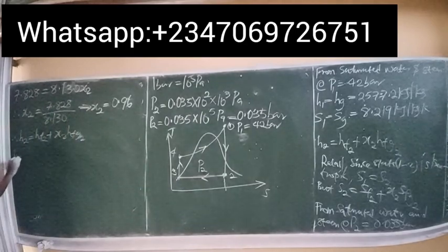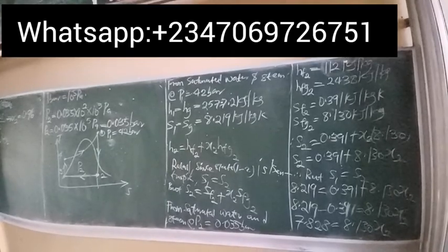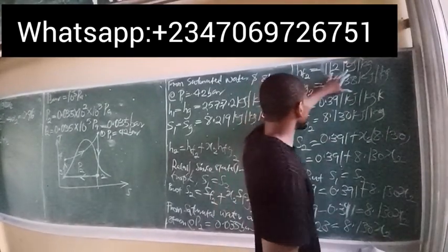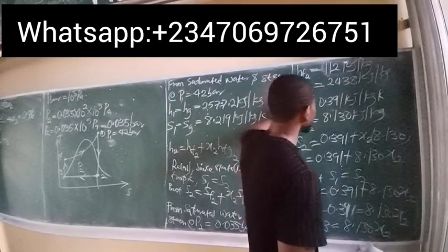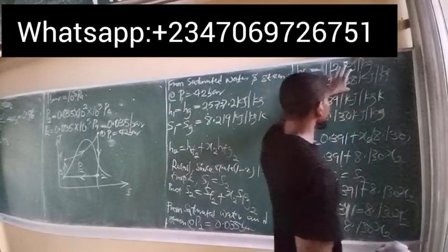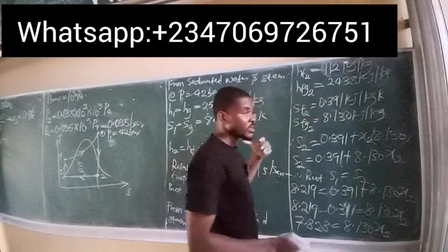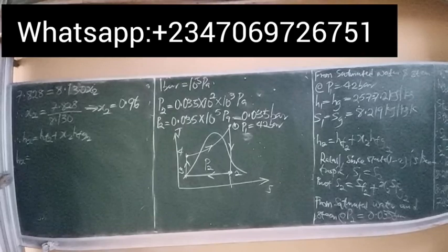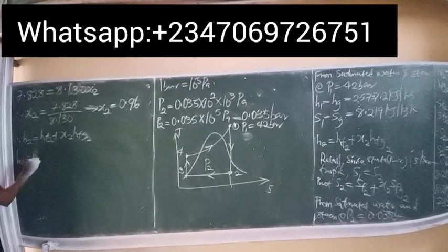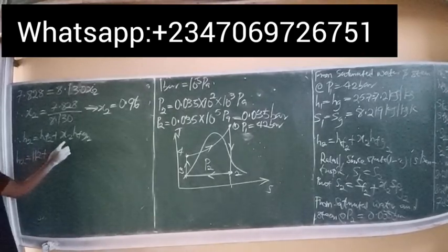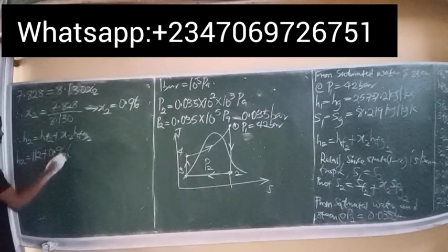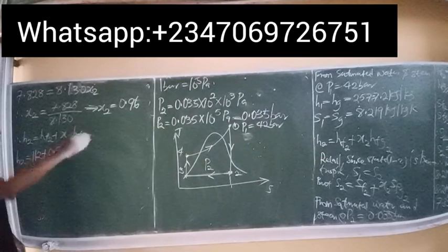So therefore H2 is now equal to, under that pressure, we obtain HF2 to be 112, and we obtain HFG to be simply 2438. So we simply carry these parameters and plug into that equation. All right. So H2 becomes HF2, which is 112, plus X2, known now as 0.96, multiplied by HFG2. Please recall that value for me.